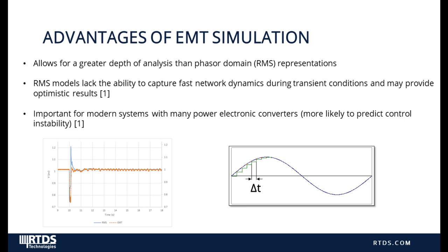The simulation time step defines the time between two consecutive outputs, and typically for EMT simulations, that's around 25 to 50 microseconds, or 1 to 3 microseconds for representing the high-frequency switching of power electronics.